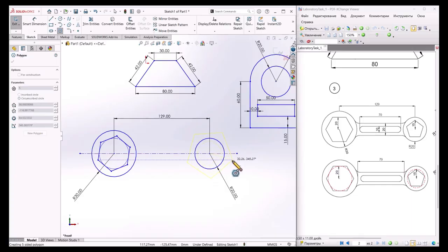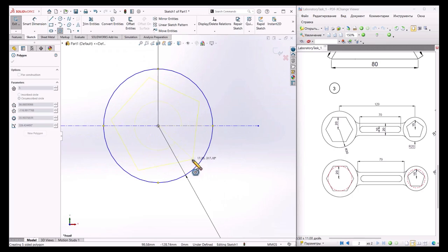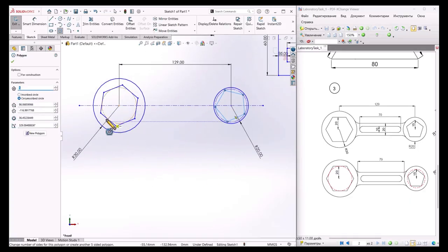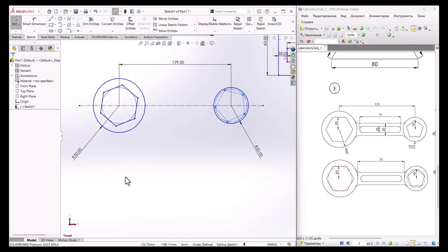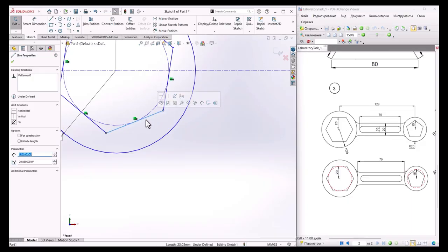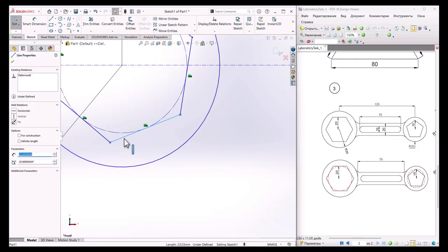Again, make it like this, inclined. Okay, otherwise we cannot find this horizontal feature, so that's why I'm making it like this, inclined. Now off the polygon, now select only one side, okay, the bottom side, that becomes a light blue.